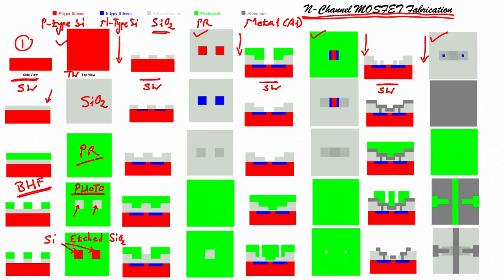the photoresist, and when you develop the photoresist, because your patterns are such that you will etch the photoresist from these two windows, this one and this one, you can see here, right, gray color, light gray. What does that mean? That you can see silicon dioxide below the photoresist. So, rest of the area of the wafer is protected by photoresist, the area which is shown by these two arrows, it is not protected by the photoresist.